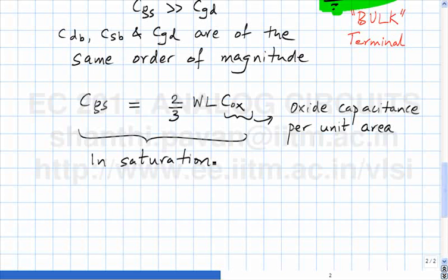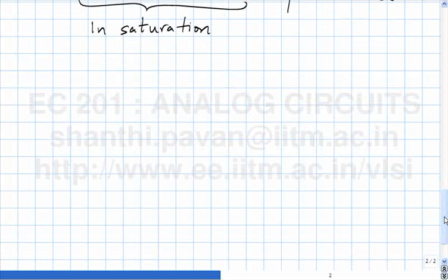So if the MOS transistor is operating in saturation, the incremental gate source capacitance happens to be 2/3 W times L times COX. How this comes about, you will only learn in an advanced device class. And as circuit designers, just like how we didn't really care how the equation for the ID versus VGS came about, we don't really care how these numbers come about, we just care about the numbers themselves. The first thing to do is to figure out what these capacitances do to me.